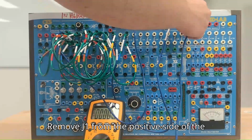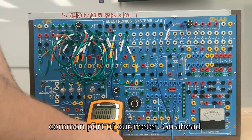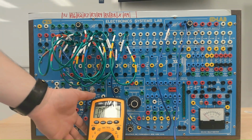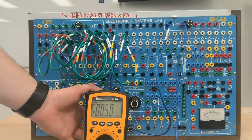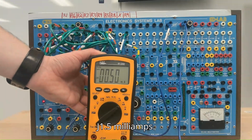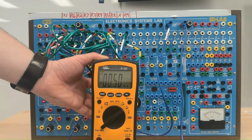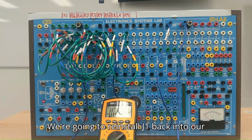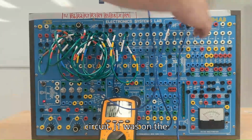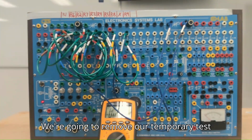Remove J1 from the positive side of the voltage source. Install that into the common port of our meter. Go ahead, turn on our trainer. Amps flowing through J1, 0.5 milliamps. We're going to reinstall J1 back into our circuit. J1 was on the positive side of the voltage source. We remove our temporary test lead.